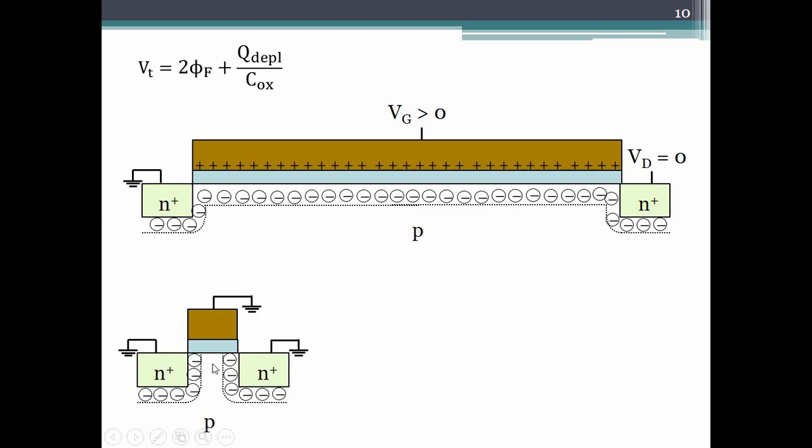And that charge is entirely due to the depletion regions of the P n plus junctions, the source body and the drain body junctions. Here, of course, this entire depletion layer charge is created by the gate voltage. Only the small region here, a little bit here and a little bit here, was already present without the gate voltage.